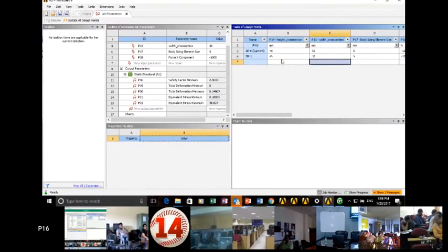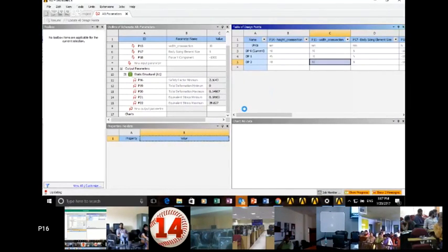So now I'll keep the height the same and I'll change the width. Then I'll again update the design points. So this is what is called a what if study, whereby the user inputs various parameters based on his understanding and then obtains the desired results. But this approach cannot tell you that the parameters which you have taken as reference are the only parameters which are creating a change in your resulting analysis.